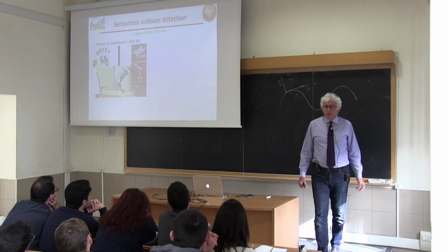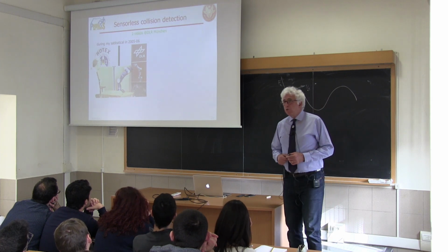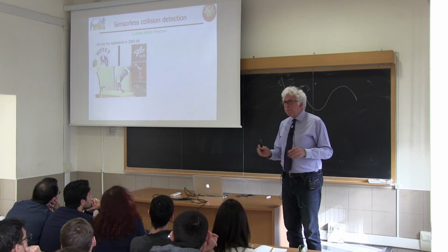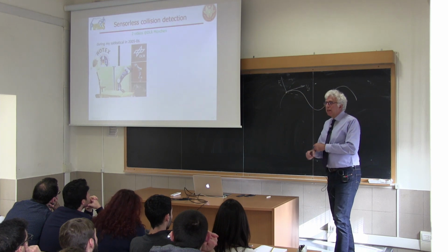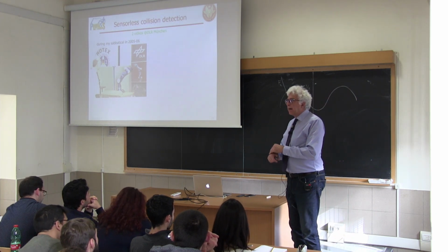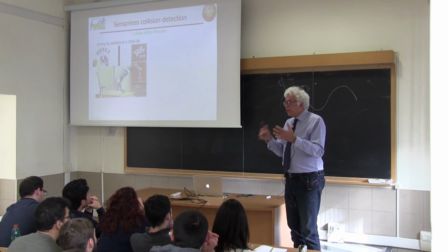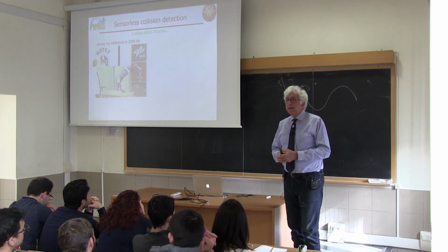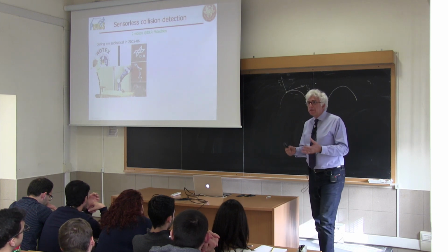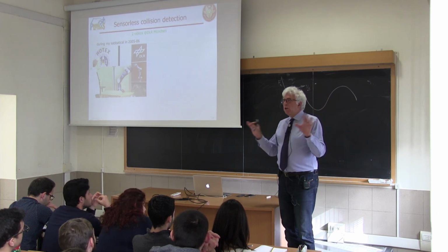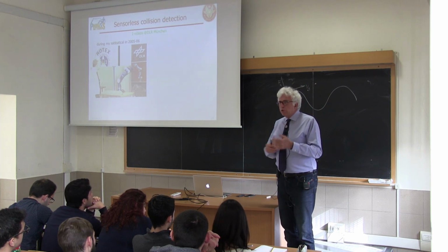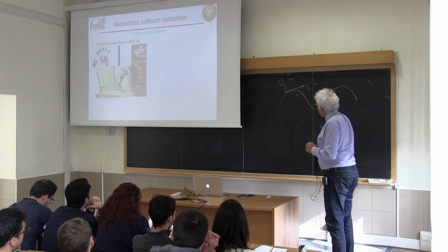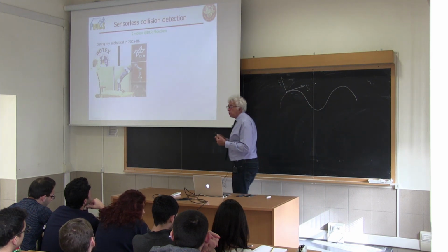Okay, so the last set of videos are related to the problem of human-robot interaction. In this case, as I mentioned, safety is really the basic requirement, something that in industrial settings you used to guarantee by putting cages around the robot, so avoiding that the human operator accesses the workspace of an industrial robot, typically even very large, huge ones, when you have given power to the motor. So the robot can only stay still, or you should use some safety precaution, the presence of a red button on the joystick, on the teaching box, and so on and so on.